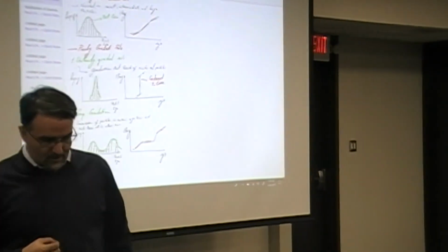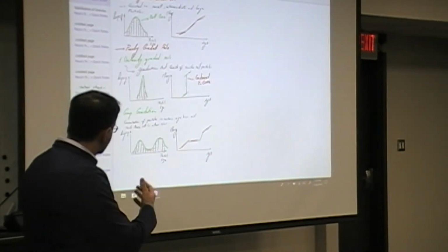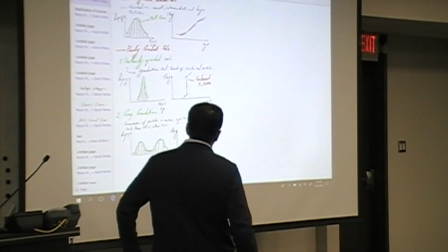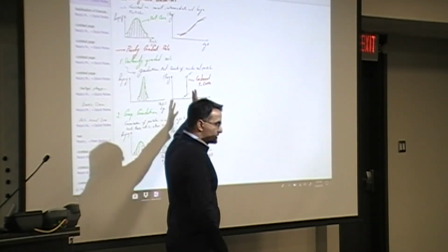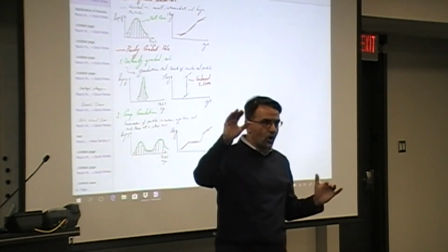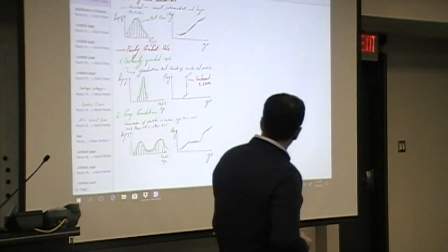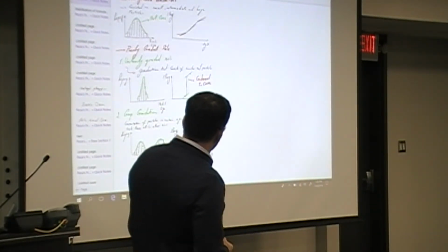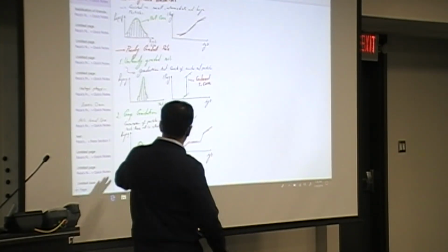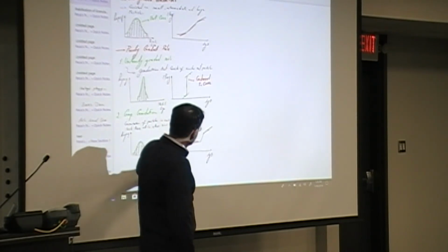The way that you can identify the shape is a condensed S-curve as opposed to an elongated S-curve. In simple terms, just draw the slopes, and that gives you a good indication. And then ultimately we have the gap gradation, which essentially follows a bimodal distribution, as you can see.